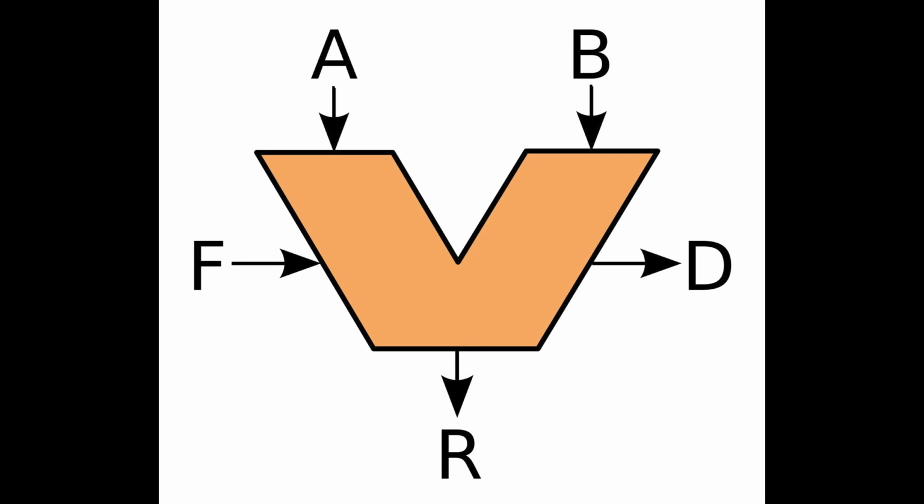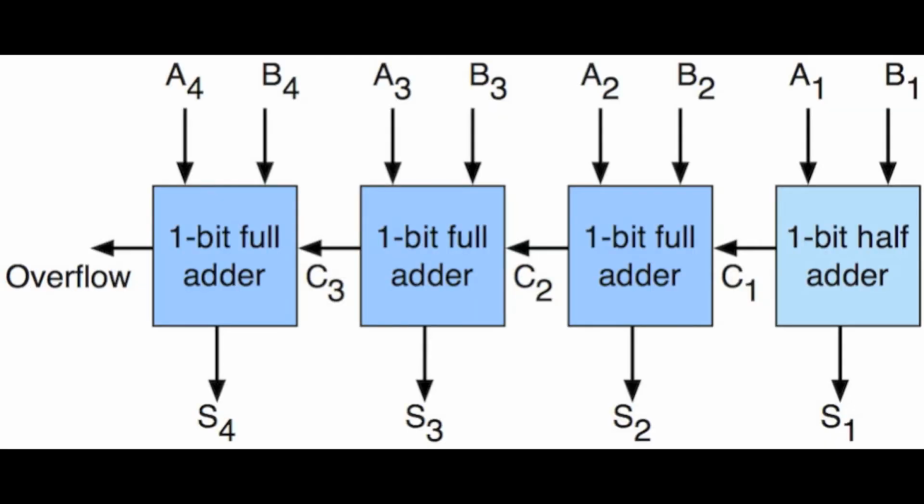In conclusion, there are many applications of logic gates and adders. For adders, it is even possible to create a logical circuit using a series of full adders to add n-bit numbers. The full adders are chained together such that the carry-out bit of one adder is connected to the carry-in bit of the next adder. The carry ripples from one adder to the next similar to pencil and paper addition. This is known as a ripple carry adder.